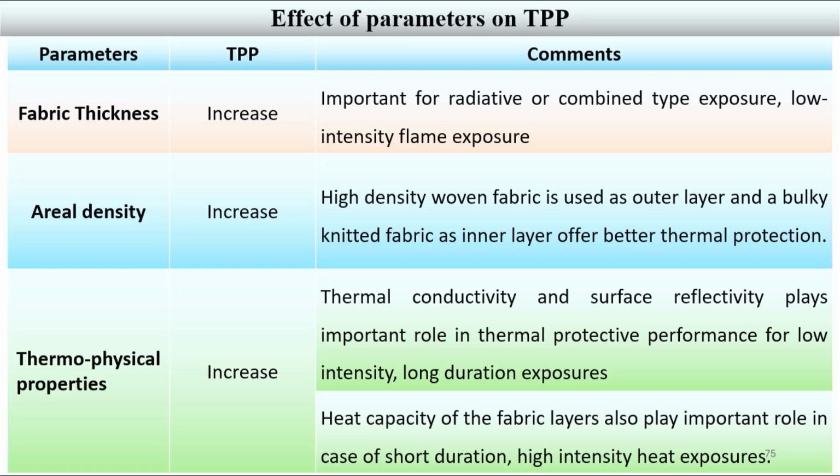Now, we can see fabric thickness. If the fabric becomes thicker, it will increase the TPP rating. Why? Because it will store more air pockets.